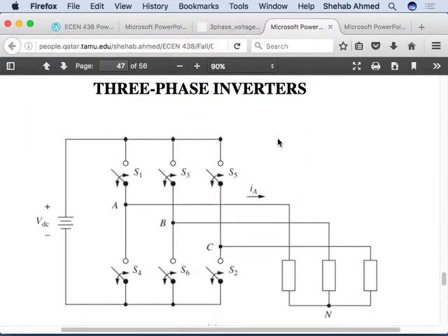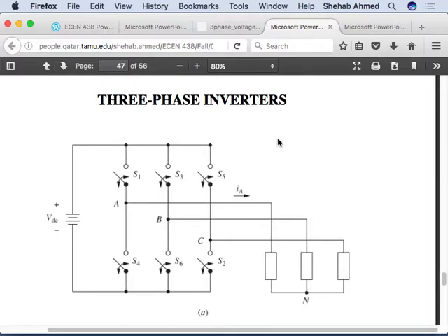And then three-phase inverters. So let's look at that. Everybody's okay with this discussion on power quality? Yes. This is what you want to see at the output. This is your modulating signal: 50 Hz, 60 Hz, whatever you want. If it's for a motor application, you're controlling the frequency of the modulating signal, as well as the modulation index, to control V over F.